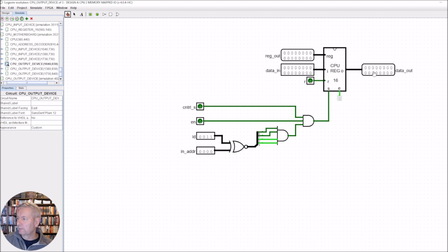So it just becomes, again, a transparent latch whenever this point here goes high. But this isn't going to go high unless these 3 lines have gone high. And again, we're going to have to have this enable here go high. So this is again coming from the address decoder, which is telling us that we're in the IO block of addresses in the memory.